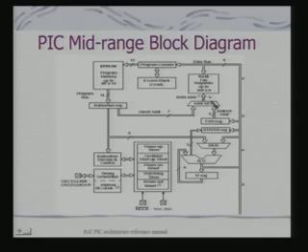Okay. So what we will find is that from this register the data would flow onto the data bus, and then it will go into this multiplexer so that it can be used in ALU for various operations. Now there are two kinds of bus structure you have found here.